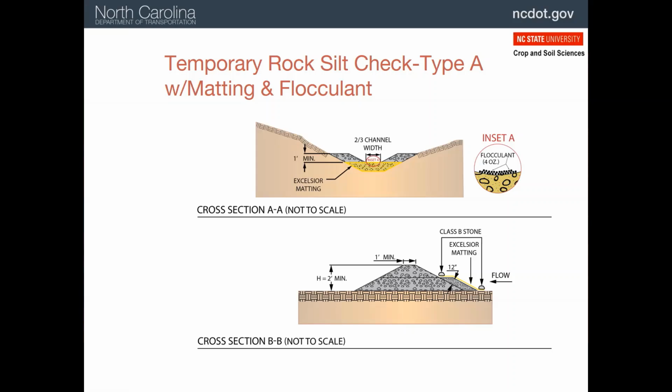Here's an illustration of that. It's essentially the same illustration we had before, only now we've got a blanket on it. You can see what they've done is they laid the blanket on top of the gravel, and put a rock on each side. There's nothing to staple into, so you just need to put a weight on the blanket to hold it in place.